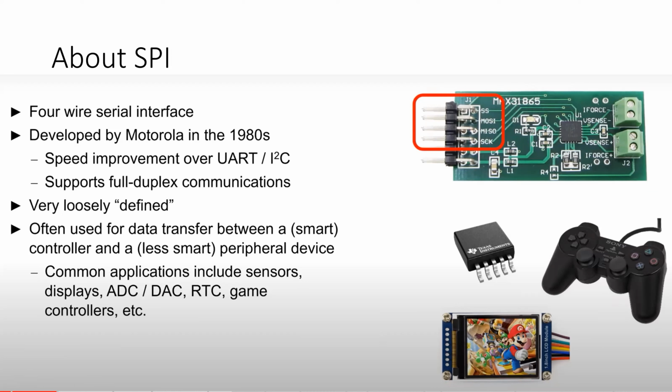Actually, we haven't discussed I2C till now. If we have the overall idea about I2C, there will be some kind of bit frames. There will be some synchronization between the clock and the data bits. So a start bit is there, and after that, 7 bits of data will be transferred to the external peripheral, which is the address of the peripheral. That 7 bits of data says the address of the peripheral which has to be communicated with the master. So there will be some kind of specification within the bit frame.